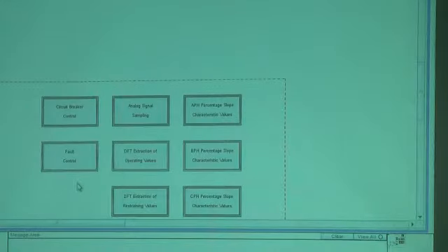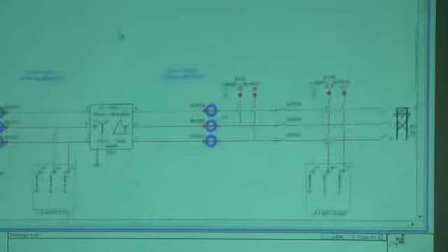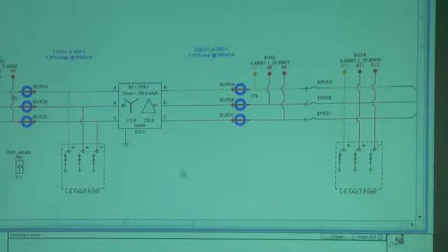So that was the 10-minute course on how to model a transformer relay in the RTDS. It's a pretty interesting simulation because you can get right down into the details and look at the logic. I have not compiled and ran this case for a number of years, but it should be good to go.